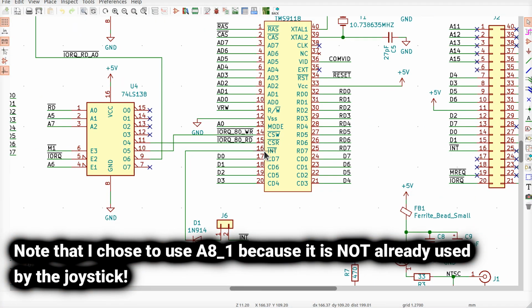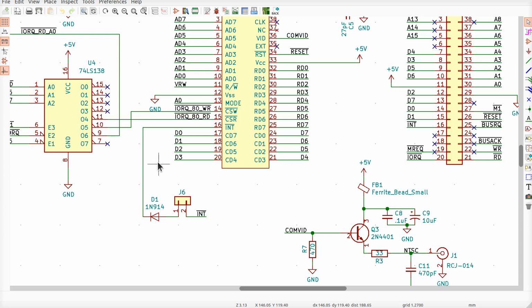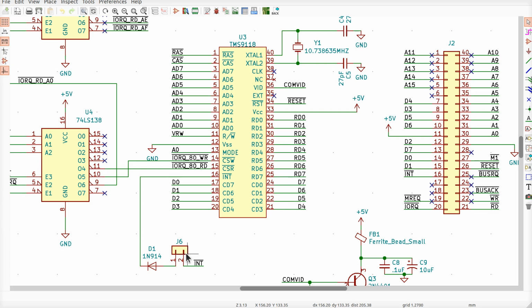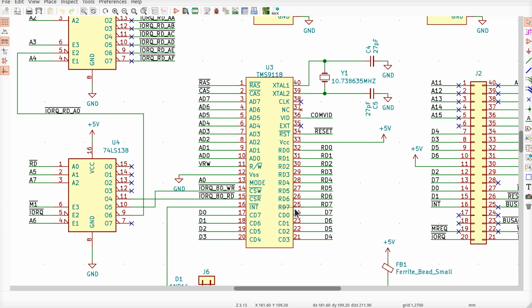So I could now, if I wanted to, put this jumper in there, put the Z80 into mode 1, I suppose, so that if it generates an interrupt, it'll go to the one and only handler. I would have to use mode 1 and not mode 0 and not mode 2 because the Z80 requires a handshake from the peripheral device if you use the other modes, which this thing does not do. So it leaves you with mode 1, which says, if I have the numbers right in my head, that if this thing ever generates an interrupt, go to the one and only one place to handle the interrupt that has occurred. And in that handler, you can then go read the frame flag bit from the VDP.